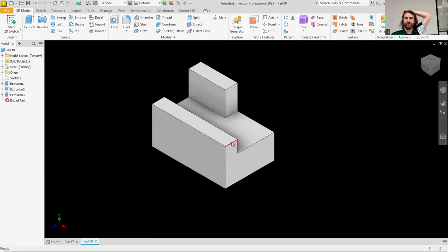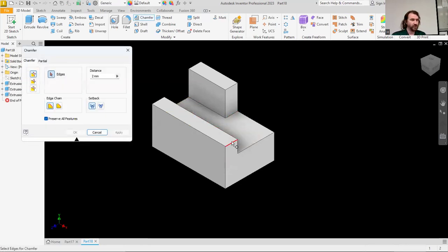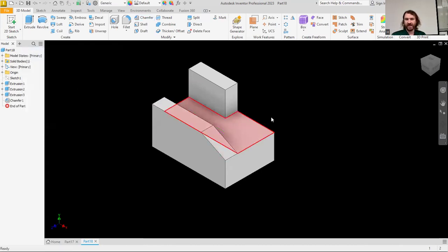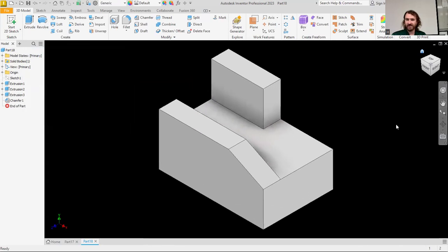Now we just need to chamfer this corner that's here. So I'm going to chamfer this corner, and it's two different distances. So I'm going to do two distances and click the corner. And now horizontally, it's 20, and vertically, it is 10. So it goes 10 down. And that is the part file there. That is lesson 42. Two pretty quick parts in this video today.